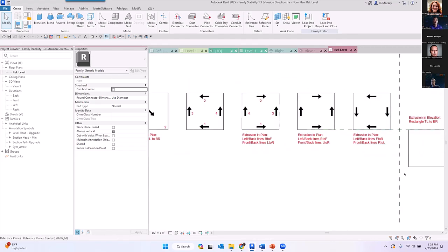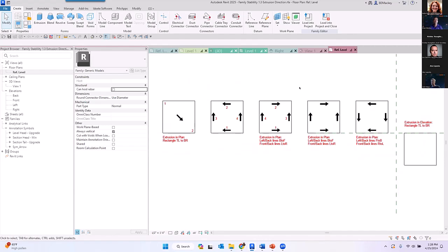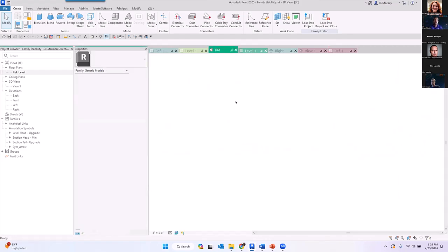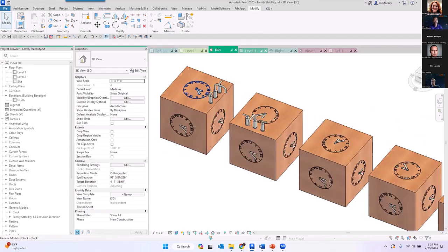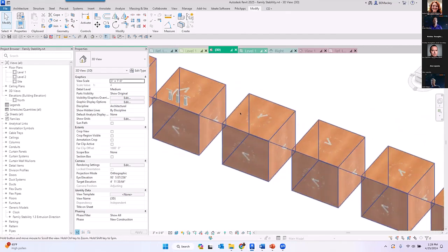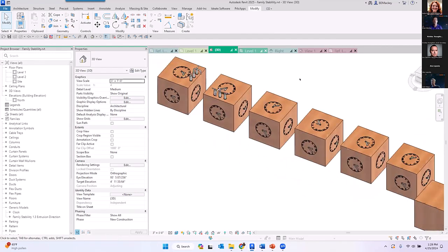I went through and started drawing all sorts of different scenarios so then I could understand when I'm back in that project, okay, this one was drawn with a rectangle going from here to here. It pointed to the right. Okay, that makes sense. It's above the second pick. But this one I went from right to left and it did the bottom down here. I never really could remember which directionality was giving me which scenario. But you can see they're all different extrusions, but all those sketch lines were drawn in different directions. So understand that everything in Revit has directionality to it.